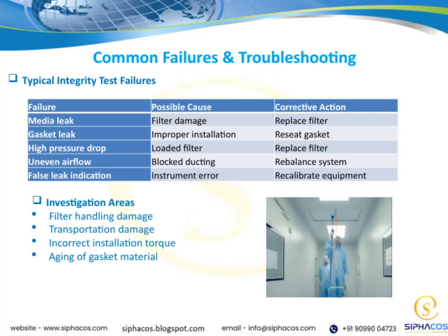Now, let's take a closer look at the investigation areas related to common failures. First, filter handling damage can occur during maintenance or installation if not handled properly, leading to leaks or reduced performance. Transportation damage is also a concern. If filters or components are not carefully transported, they can arrive damaged and cause issues later on.